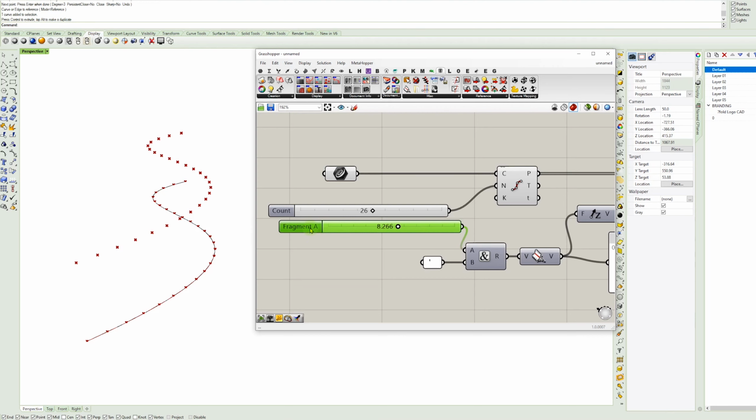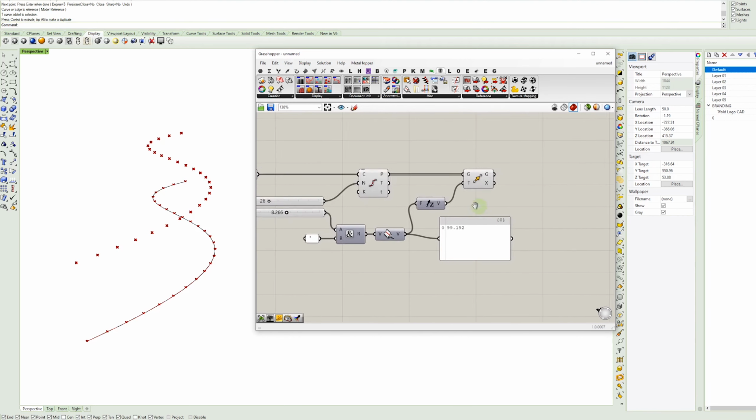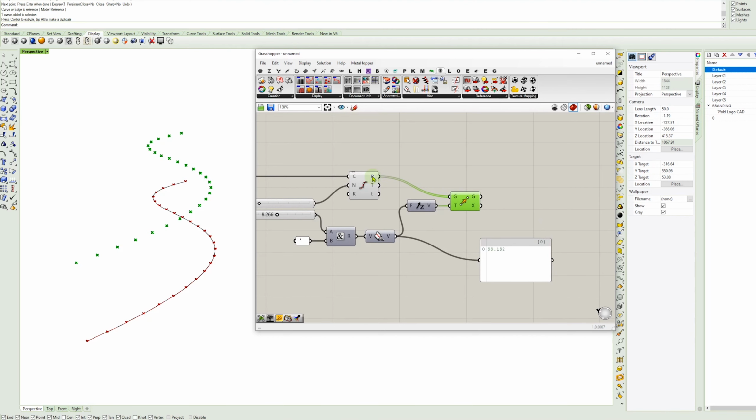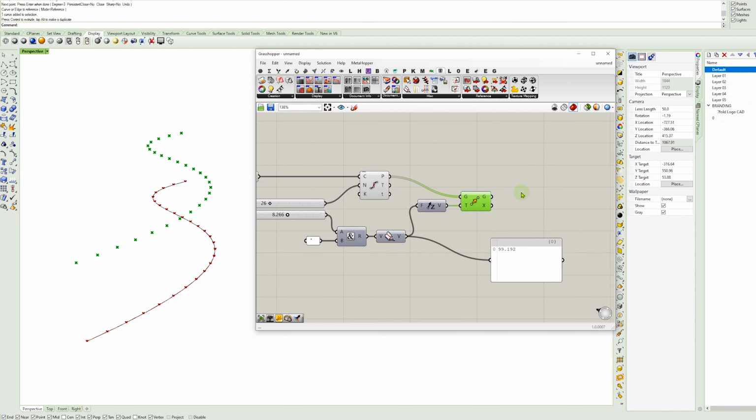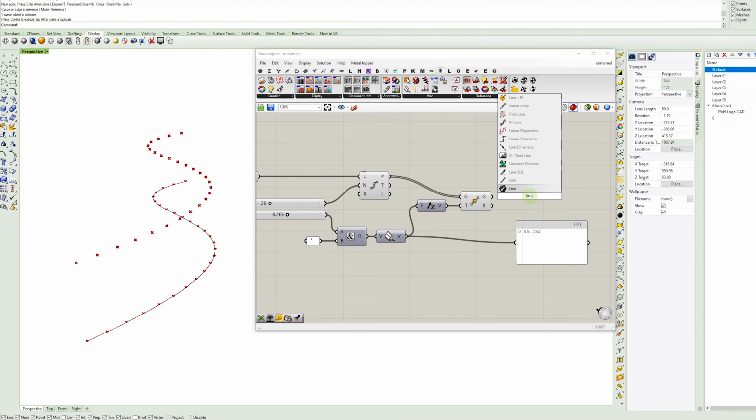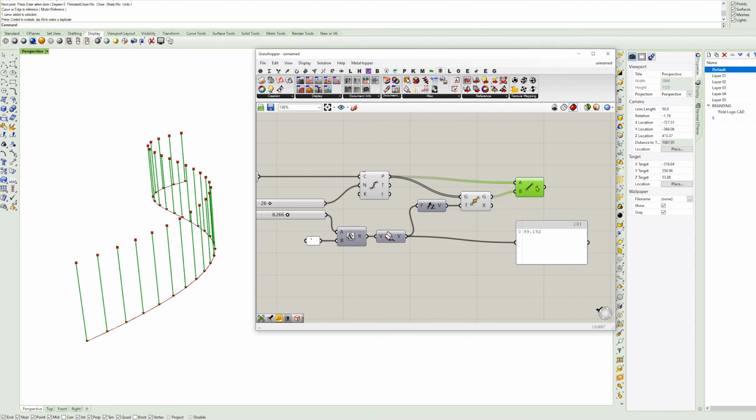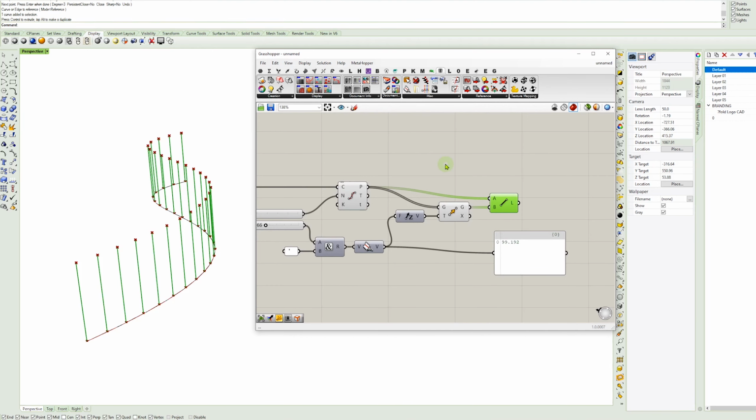Okay, so I'm just gonna right click on this input and just change it to height of geometry. You can say height of studs, you can say height of whatever. I'm just gonna keep it neutral. And then we're gonna come over here, and now we wanna bring these 2 points together. Now, what's interesting is if I was to do it just as is, I could do it as a line. That's easy enough. But my preferred way, so I could do B and I could do A here, and that's gonna create that line. But my preferred method is actually to graft it.